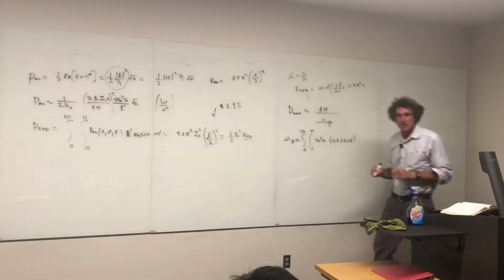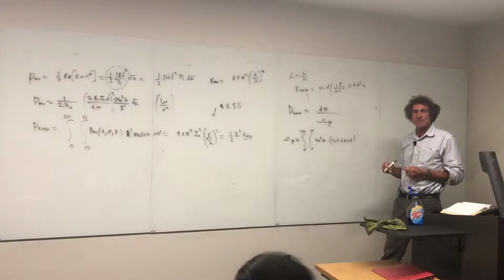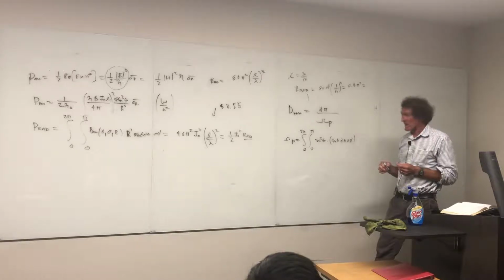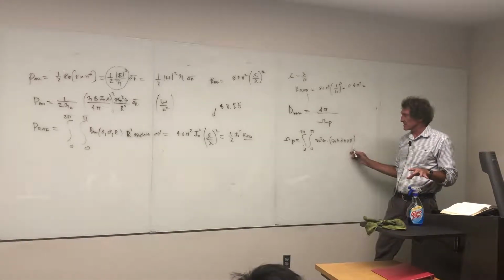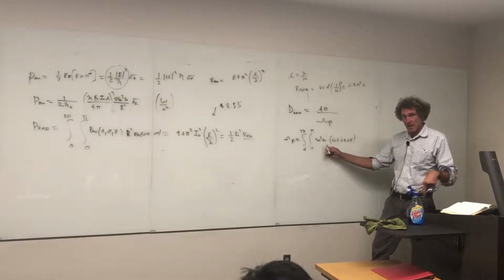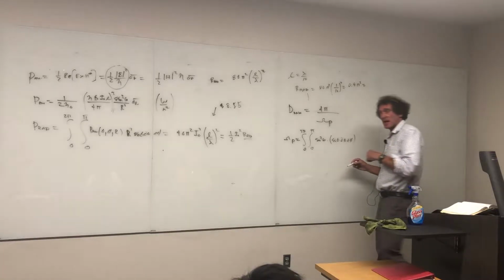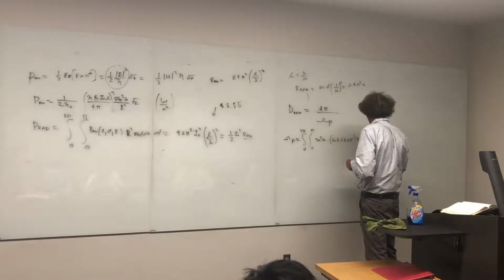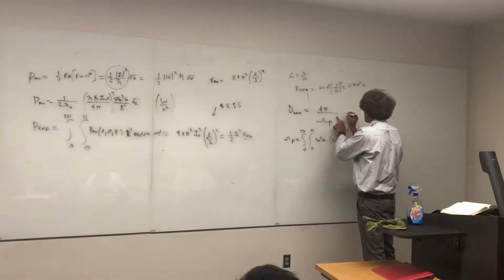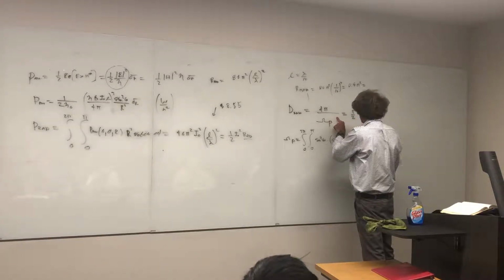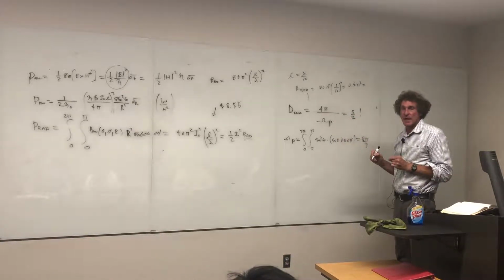Everybody remember doing this? We did this, right? I really was trying to emphasize why it means what it means. That's the solid angle that goes here that gives us the directivity max. Now, I want to make sure everybody sees this. You remember sine squared becomes 1 minus cosine squared, right? We do the integration. After the integration, this is 8 pi over 3, correct, class? You stick that into here, and this becomes simply 3/2. The directivity of a short dipole maximum is 3/2, or 1.5.